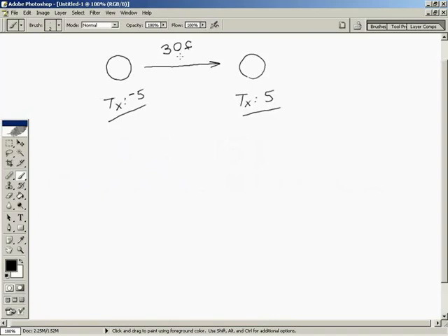So now I need to record some keyframes. I'm going to indicate a keyframe as a big box, if you will. Giant box. This is a single keyframe. What is stored inside this keyframe? Well, we're going to store what our frame currently is, and we're going to record the first keyframe at frame 1. So this is where the animation begins. And what is our attribute? Translate x, and what is it currently at? -5. So when we record the very first keyframe, this is what we get. We're saying at frame 1, translate x is equal to -5.